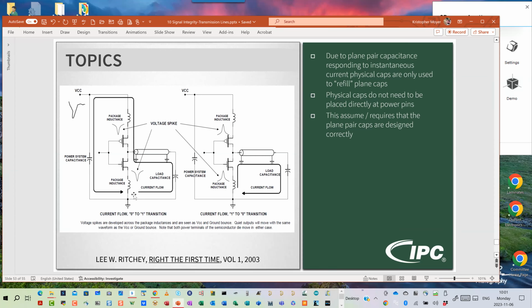Now, I'm going to qualify that by saying there's lots of nuances in there. There's also frequency dependence. Certain caps say, here's the maximum frequency you can switch at. That's usually more in your old school oil-filled, polypropylenes and aluminum electrolytics and so on. The ceramics typically don't have hardly any problems like that from an aging standpoint. Temperature, yes. Vibration and shock, yes. Moisture, yes. Over voltage, yes. There's usually not. Okay, thanks.